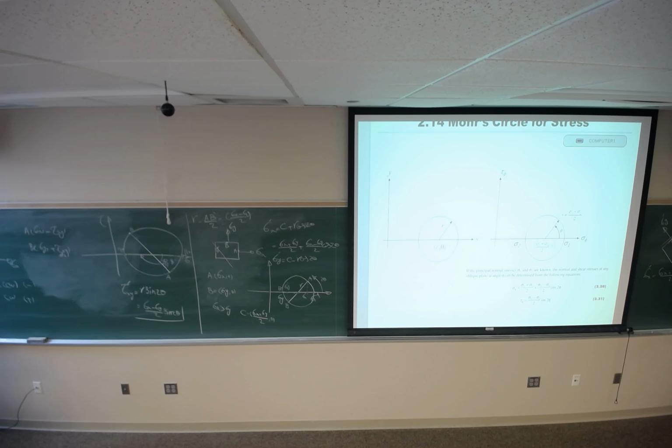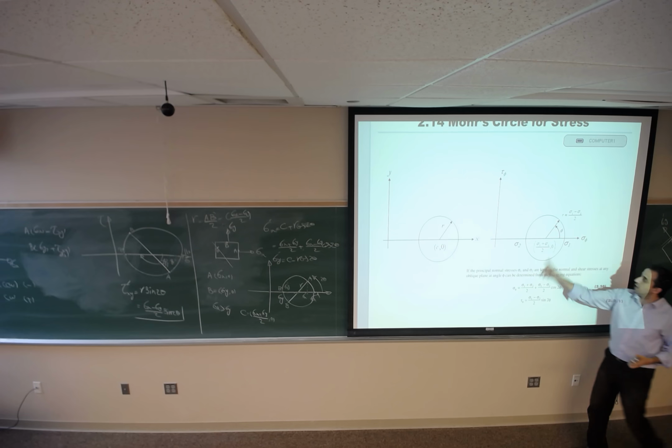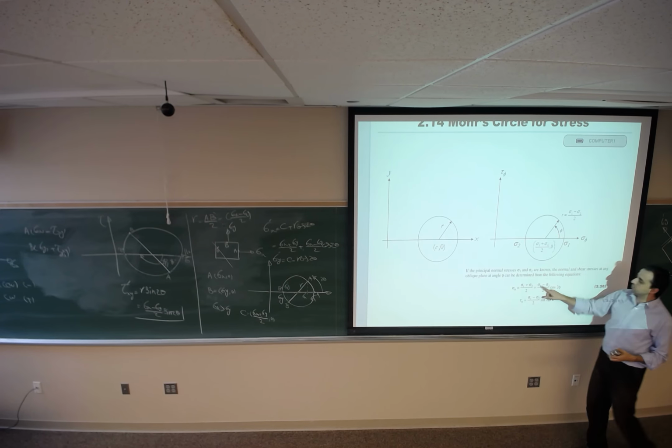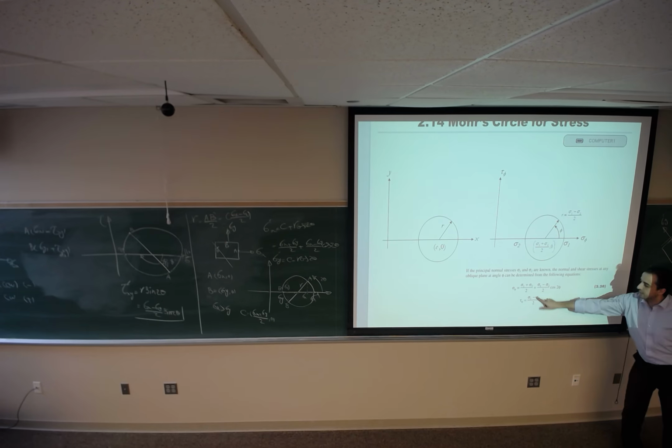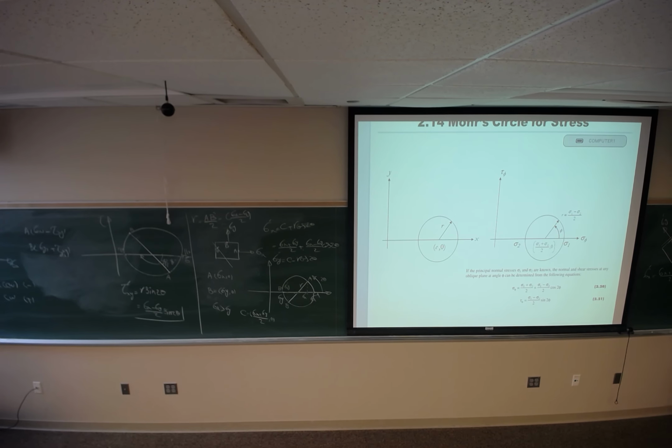Any question on this? In this slide, you can see the result: sigma phi is going to be sigma 1 plus sigma 2 divided by 2 plus this term, and shear stress is going to be r sine of 2 phi that I have already.